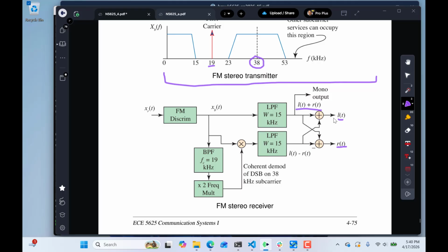I don't know if you've been thinking this through, but radio standards generally have to support legacy. So the legacy FM broadcasting was sending a monaural or left plus right signal. And then when this was invented and added to the standard, people that had the FM stereo receivers could get access to the stereo sound.